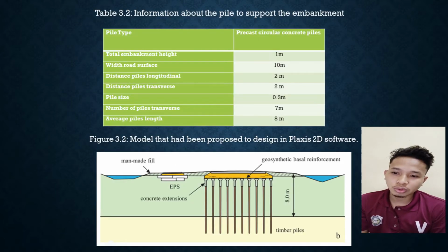is constructed by the subsequent installation of piles, pile caps, and a reinforced embankment. The geosynthetic reinforcement is placed at the embankment base, which is a basal reinforcement. In this case, the embankment consists of recycled, crushed demolition waste aggregate, mainly concrete, with friction angle 35. This material also acts as granular road base.